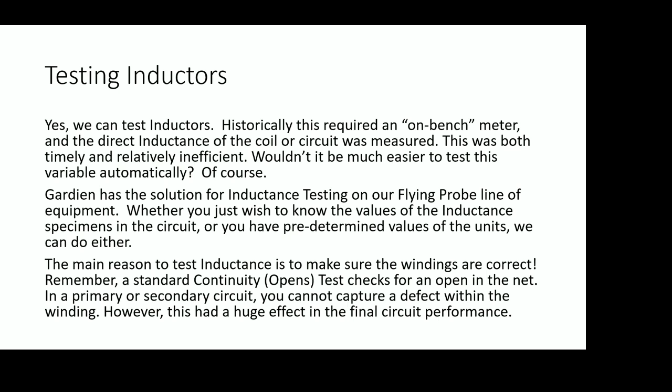And so reliability wise, your AOI can probably give you a pretty gross analysis of that type of scenario. But when you get down into, especially in microwave technology, where you're designing in capacitance and inductance, that component of reactance is extremely crucial in higher frequency circuits. So I really think we need to get into the inductive actual test rather than just relying on standard ET, open shorts, and AOI, even though those are valuable tools.